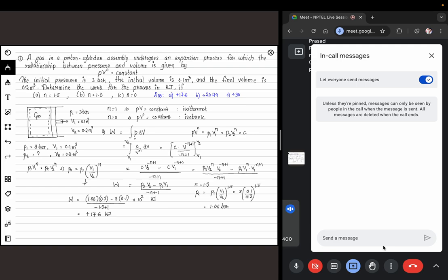So in this particular case, what would be the work done by the piston? Okay, area is not given, but even without that, you can assume that who is resisting the motion of the gas over here is essentially the atmosphere. The gas is trying to expand, and the atmosphere is trying to stop it. So the entire work done by the gas is used to push the atmosphere, and none of it is actually resisted by the piston.